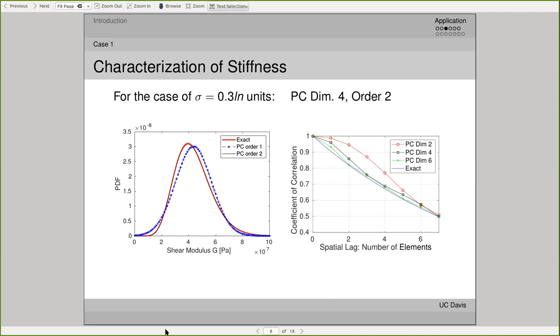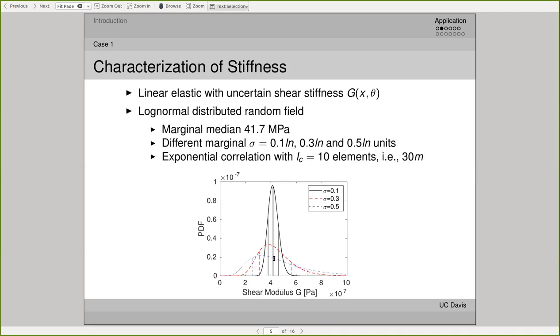Heshan, can I just add something? It is important for some of these physical stiffness fields, physical mechanical fields, to use distributions different than Gaussian, because in this case it's log normal. You cannot have stiffness that goes negative. Now, of course, if you use a normal distribution, it's going to be a tiny tail that might extend into negative, but it's not a good idea. So in this case, we say it should be something other than normal distribution, so log normal distribution. As you can see on this graph, the field is completely positive stiffness. That's very physical, and that's the way it should be.